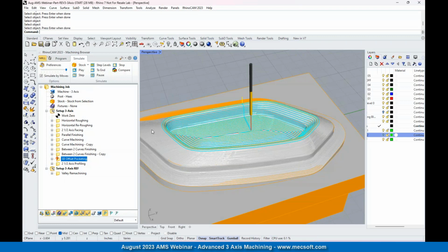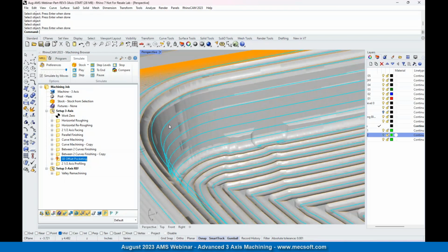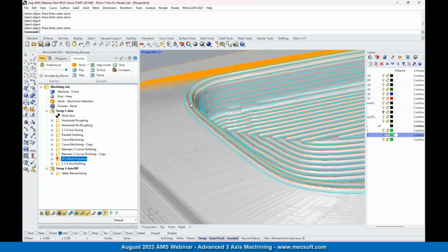It's a very sophisticated algorithm behind it, and it actually takes the curve and offsets the curve based on the surfaces below. It's really not doing projection. It's actually doing offset on the surfaces. That's why close to the vertical areas, the vertical offsets seem very constant all around.